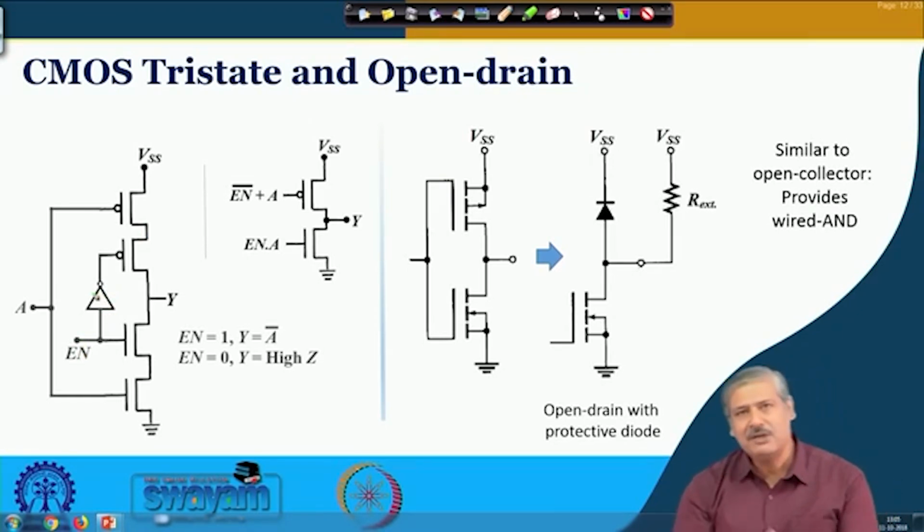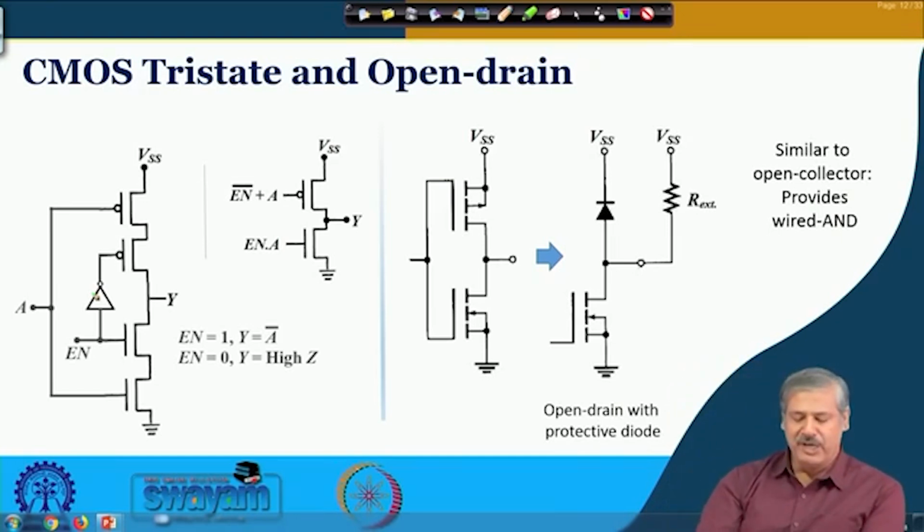Okay. So, what does it do actually? In the inverter this En is 1. Okay. So, this NMOS is on and this is inverted, means this is low. If this is high, this is low. This low means this PMOS is also on at that time. So, the output at that time will totally depend on whatever is the input. So, when En is equal to high, this is on, this is also on, and output follows the input. There is an inverter logic, so it will be the inversion of it.